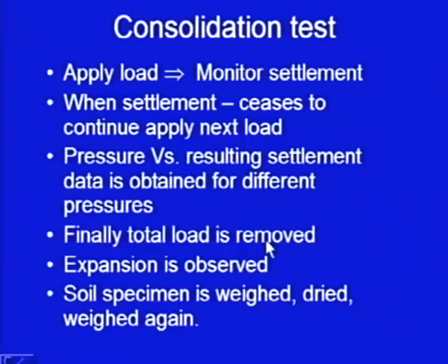Finally, the load is removed. You can also check whether there is some expansion after the removal of the pressure. Now, the soil specimen is taken out, it is weighed in saturated condition, then it is dried and weighed again.